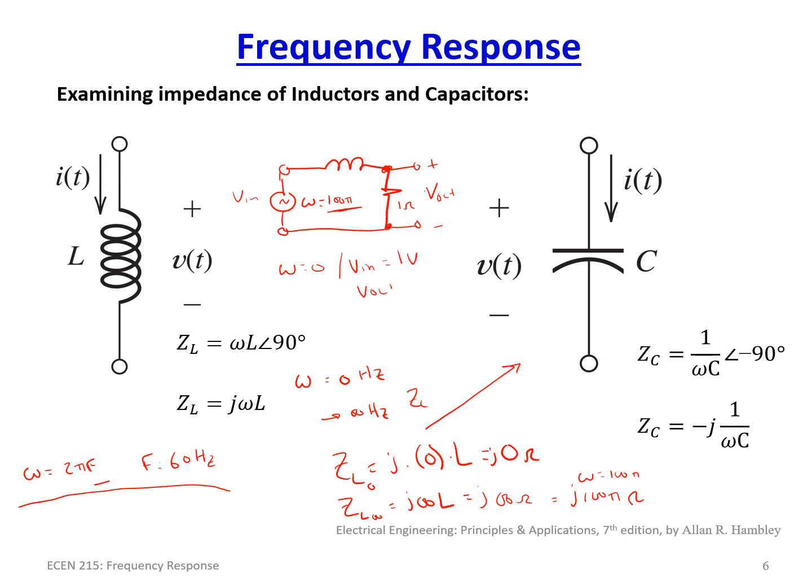V out in this case would be equal to 1 volt, because this is a voltage divider, and this right now is 0 ohms. So this basically is effectively a short. So we have V in just tied to V out.